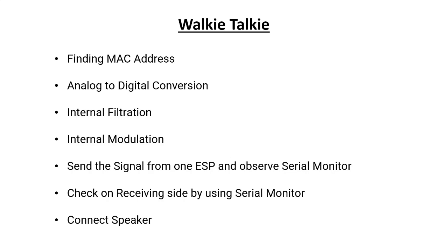And one more thing: if you use I2S, I mean an I2S microphone, it automatically converts the signal to a digital signal. An I2S microphone gives output digitally, so you don't have to convert your voice into a digital signal inside the ESP.